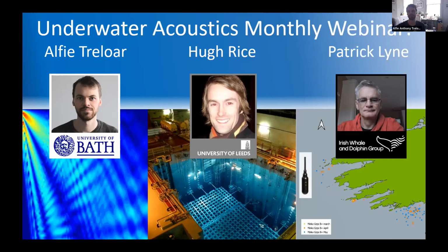You can customize your scenario entirely from your seabed composition to your sound speed profile. So it's scenario agnostic, but the main things that change obviously are your sound speed profile and your seabed composition, which changes how much reflection you get of the acoustic energy. So yeah, you can modify it to model anything anywhere.